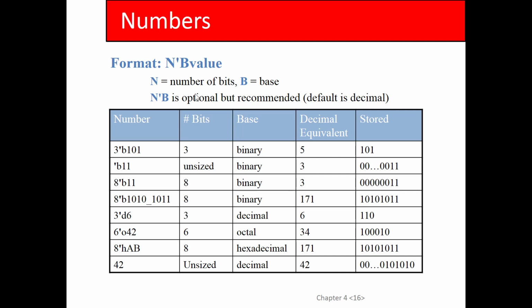So you just take off the leading bits in that case. So this is 11010. Now you might say, wait a second, I thought every hex digit's got to be 4 bits. No, not necessarily. If you say in Verilog 5'h1A, that means that this first leading hex digit can only be a 0 or 1, because if you made it 2, this would require 6 bits, and it would be invalid, right?